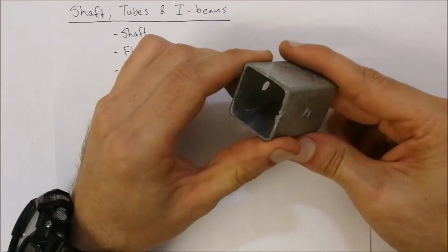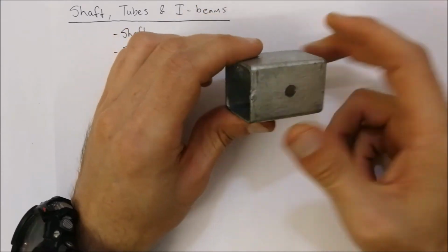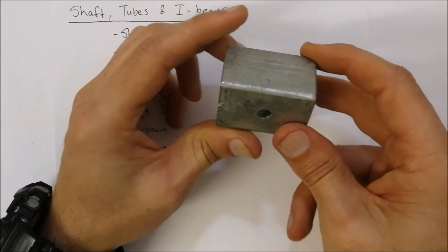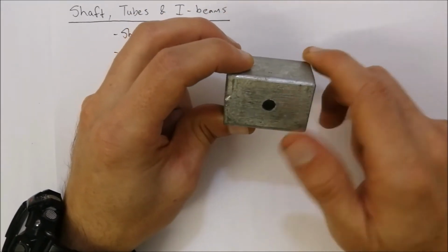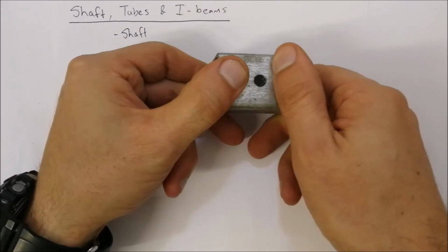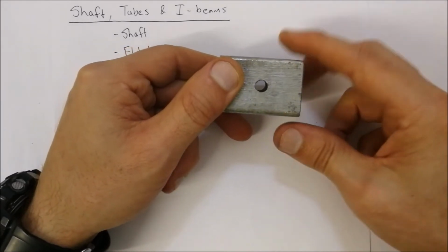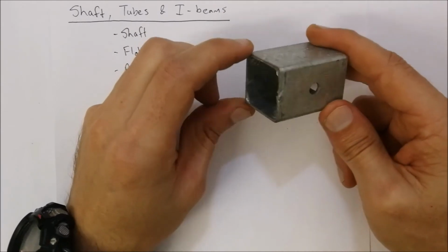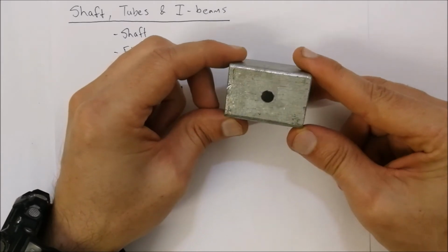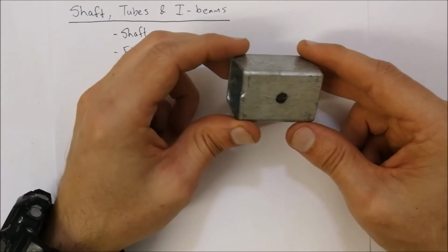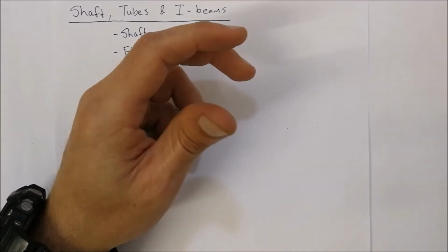So that gives your square tubing strength, because we've got these flat bars on either side over there. And so this square tubing won't be easy to bend upwards, downwards, into the page, as well as out of the page, depending on which shape you're going to have your arch going. And so square tubing can be quite useful when you've got some structure that's got quite a bit of weight on it. It needs to be strong, and there might be forces acting on it in different directions. This will be quite a useful piece of material to use.